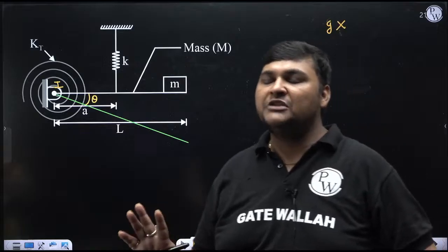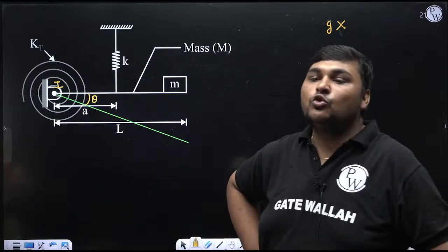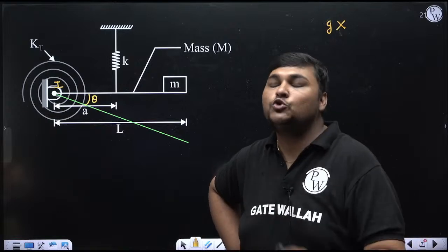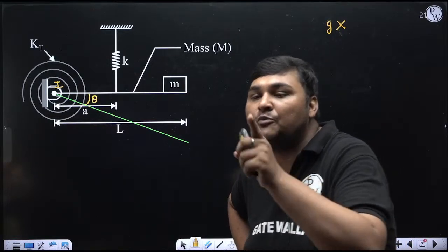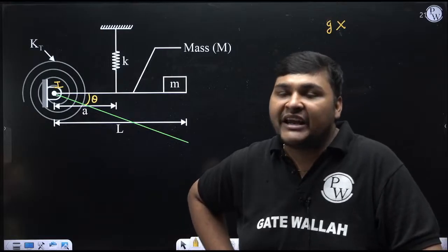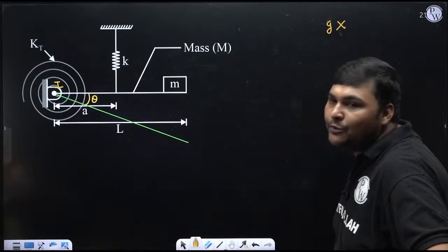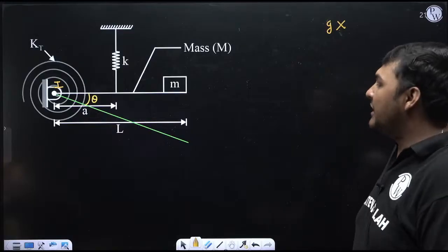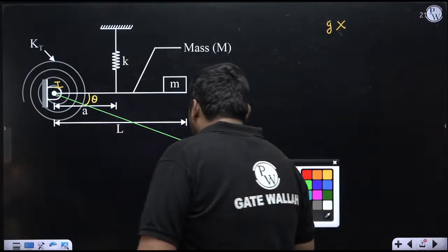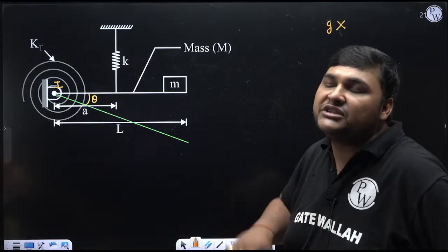When I say forces, I mean both forces and moments. And mainly we have to consider two types of forces or moments. I am not saying two forces will come, I am saying two types of forces and moments. One is restoration and the second is inertia. Inertial forces and moments you already know, but here I am first explaining how to calculate the restoring force and moment.